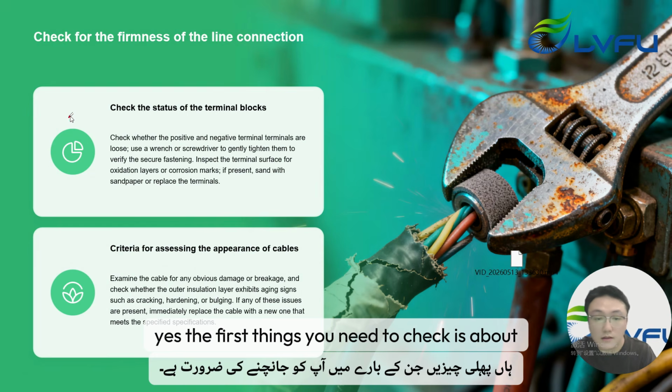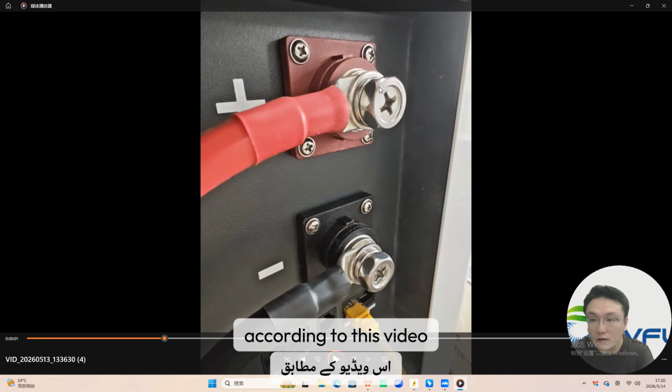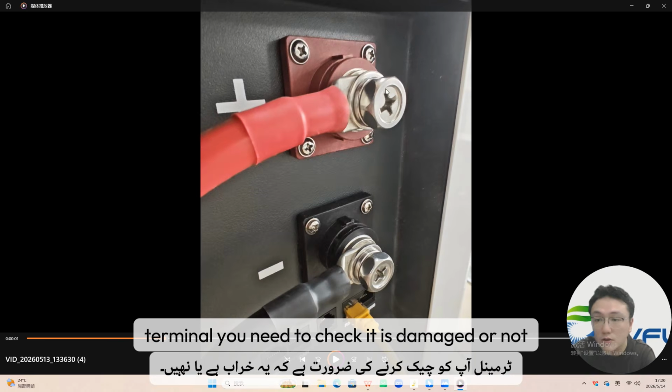Next is the physical connection check. The first thing you need to check is the terminal blocks, and the second thing is the cable. According to this video, you first check the terminal, the positive and negative terminal, to see whether it is damaged or not.